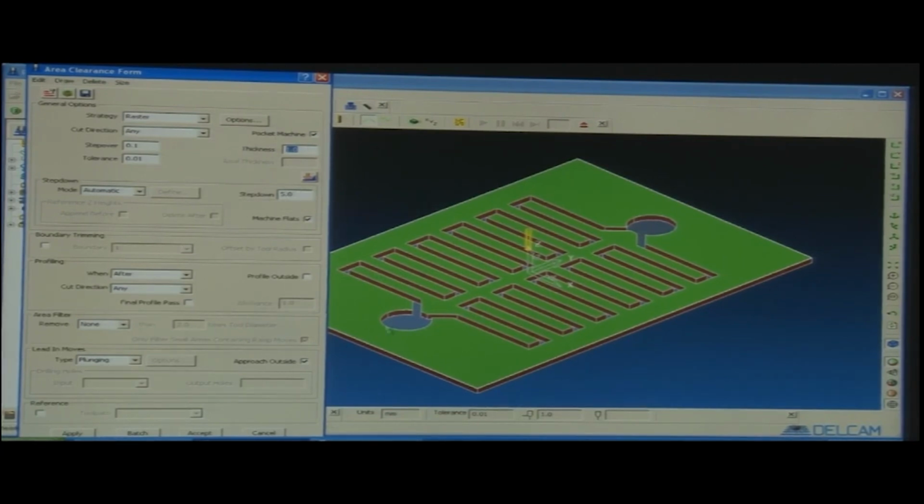When the repetition of certain pockets is there, the software will by itself pick whether they are pockets or not. We can check it or uncheck it. So, it can machine areas pocket by pocket. There are certain ways to do machining. Thickness can be put here. Whenever pocket machining is needed, the software is intelligent enough to identify that the pockets are there, and will pick that.